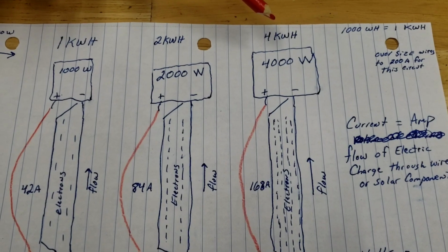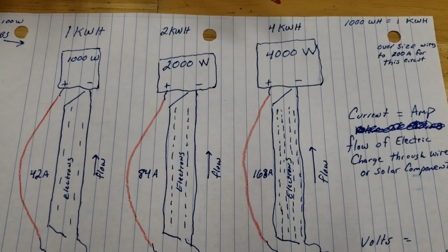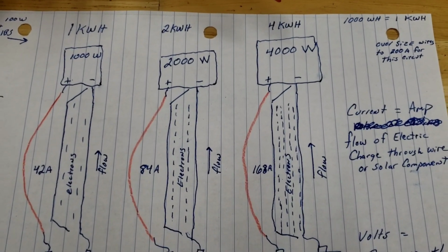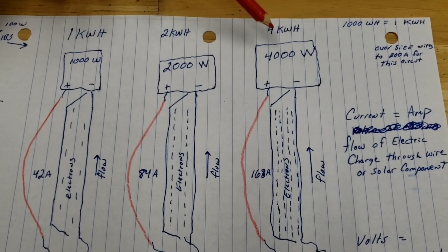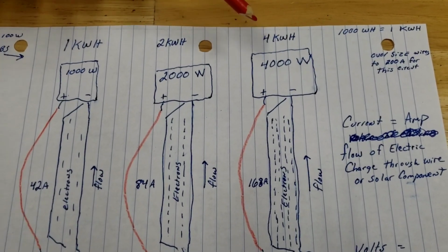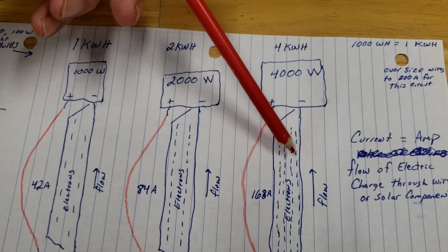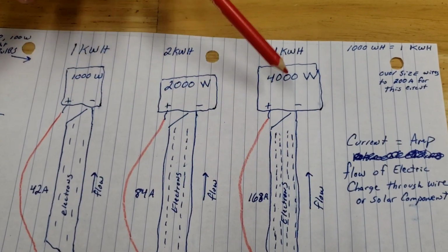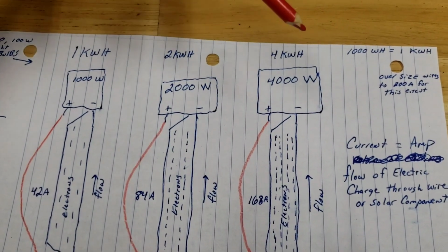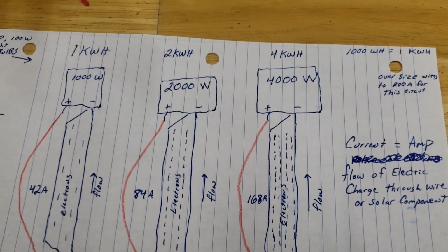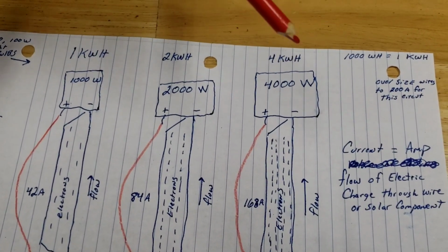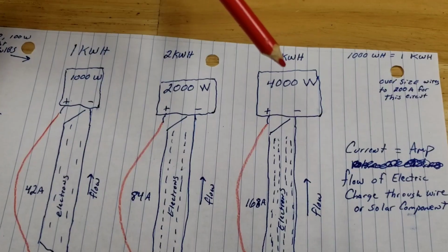One of the experienced guys mentioned to me that most of your problems in solar with fires are people undersizing their wires, and then when they get to these real big amp draws, the wire can't handle it. So if I'm wiring my trailer, which is basically wired to run all of these for the most part, I'm at 3,500, it's pretty close.